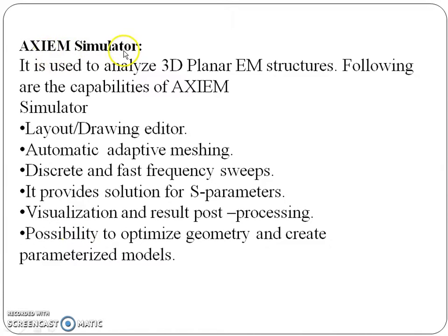The Axiom simulator is used to analyze the 3D planar EM structure, and here are some of the capabilities of the Axiom tool, which can be used to draw the layout, or in the layout we are going to draw the structures, and then we are going to analyze them for the discrete and fast frequency sweeps. It provides us with the solution for our S parameters, and then we can also optimize the geometry and create the parameterized models.